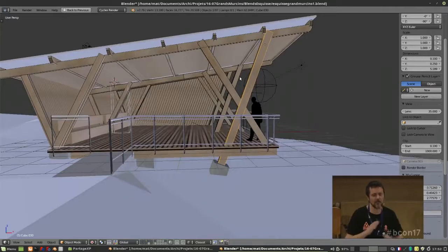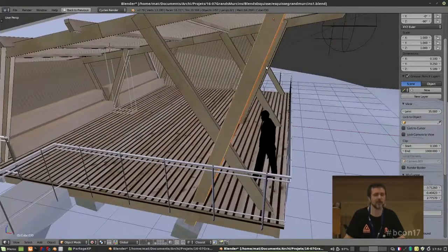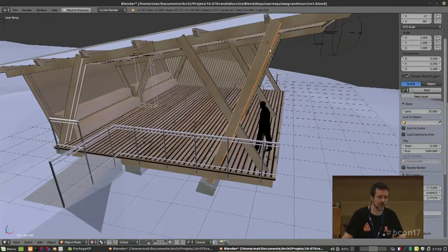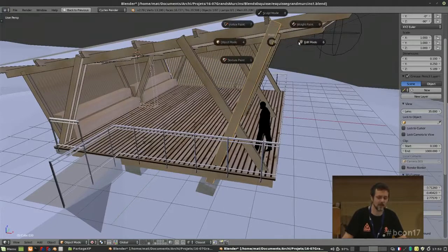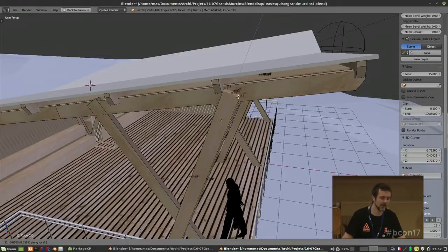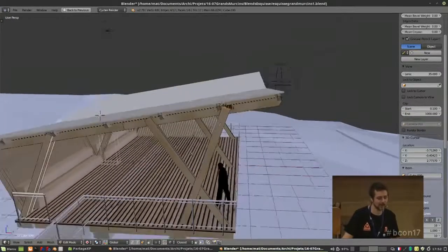But then I had to play with the angles, and it was quite easy in Blender. The only thing to take care of is to respect the local axis. So I kept in mind that for every cube, the length of the wood is the Z local axis, so that if I want to change the size of this part, I just select the point here, or the face here, and I do G Z Z, and I can move the part. So if you just respect this small rule, you are sure to have everything aligned correctly.